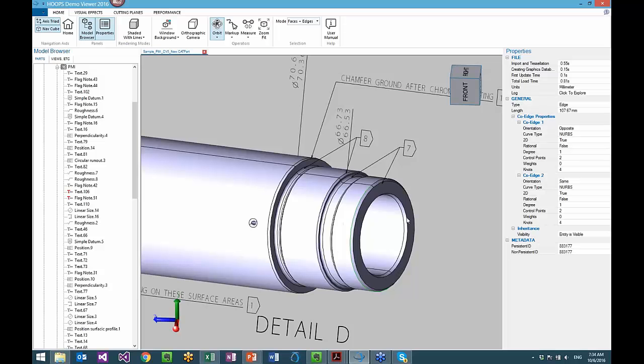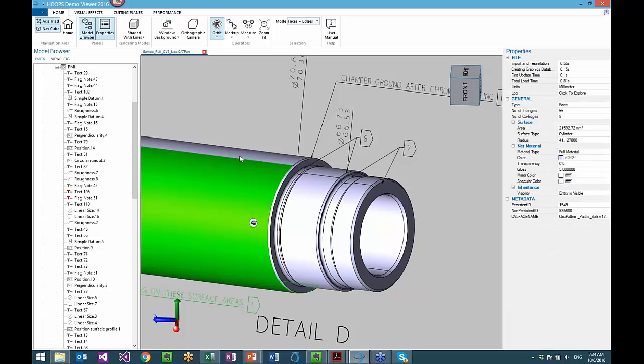What's important about this is this information here that we've extracted from the CAD file is exact geometry. And so here I have the cylinder as it was defined in CATIA, the edge data as it was defined in CATIA, and we read that natively without any conversion, and we make it accessible through this format that Dave was describing called PRC. And that's really a superset of all of the different ways CAD packages can represent their data.